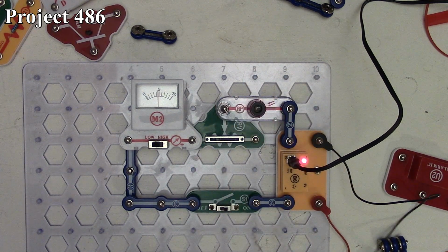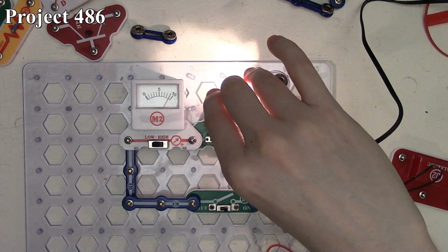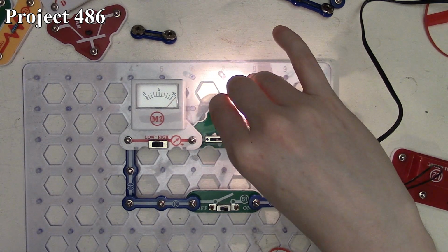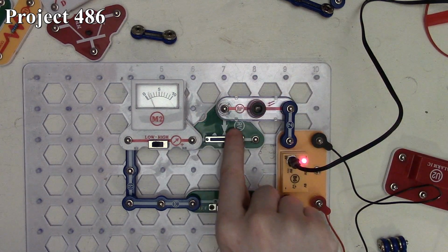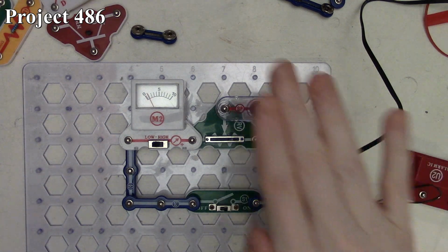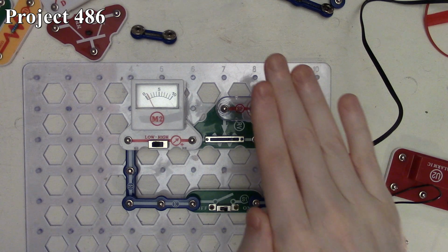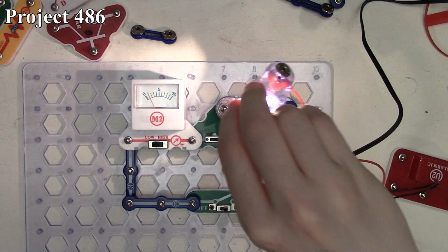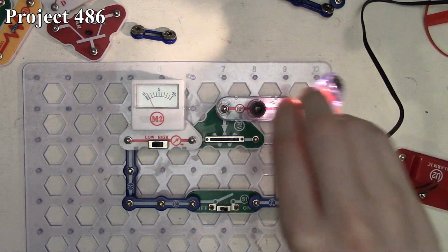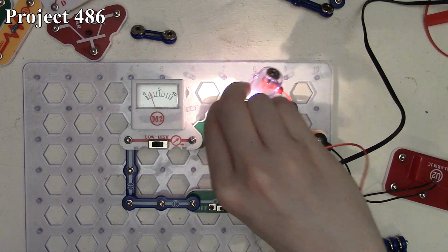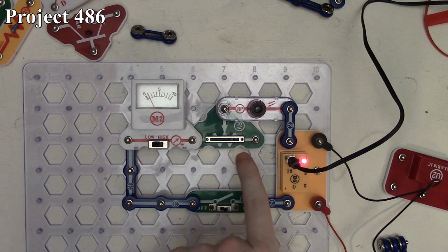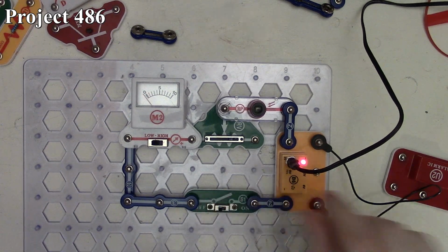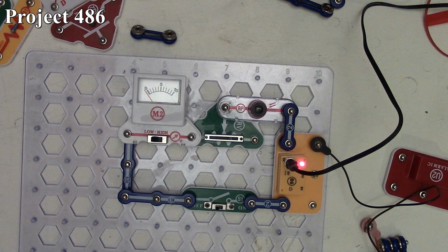Now, of course, if I bring the 6-volt lamp over and put the light in there, well, now it goes even more to the right, almost full deflection. Now, if we bring the variable resistor all the way to the right, well, now the circuit is less sensitive to light there, because now we only got maybe about a milliamp going through it. And bringing our light over, it doesn't really increase it that much, because again, it doesn't affect it that much having so much resistance on the circuit there with it set to the right. So that is how project number 486 works.